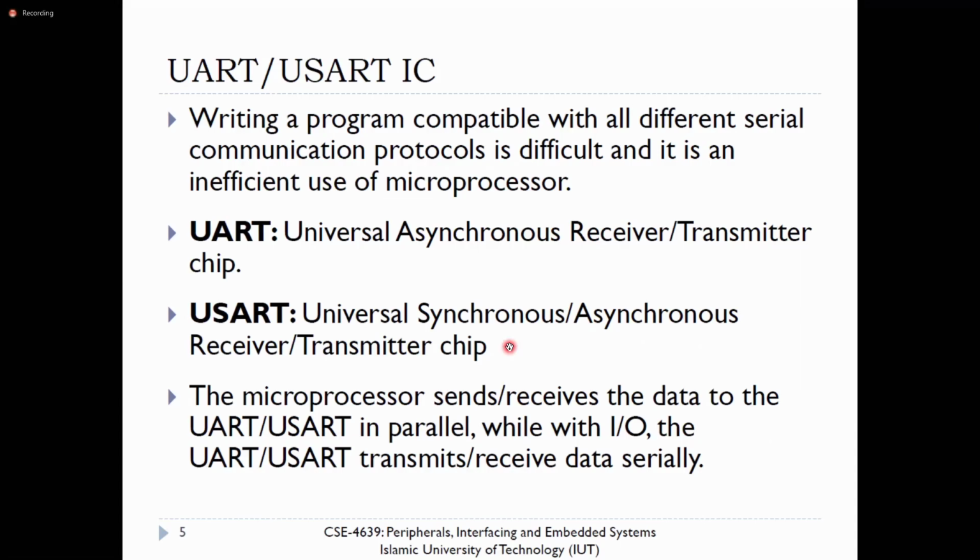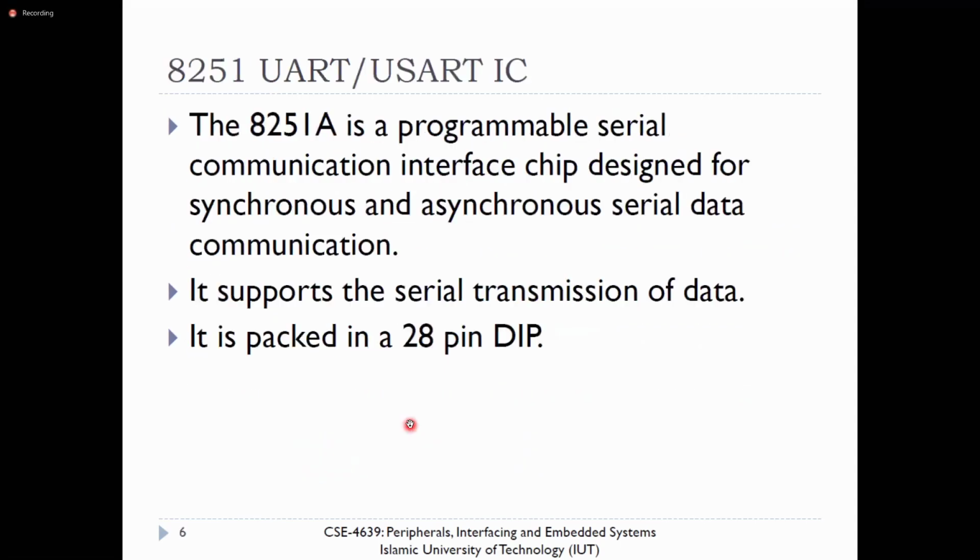One is only asynchronous, and the other supports both synchronous and asynchronous, so this is more versatile. The microprocessor sends and receives data to and from the UART or USART in parallel, while the USART transmits and receives data serially. So towards the USART, the microprocessor sends data in parallel, but towards peripheral devices, the USART or UART sends the data serially.